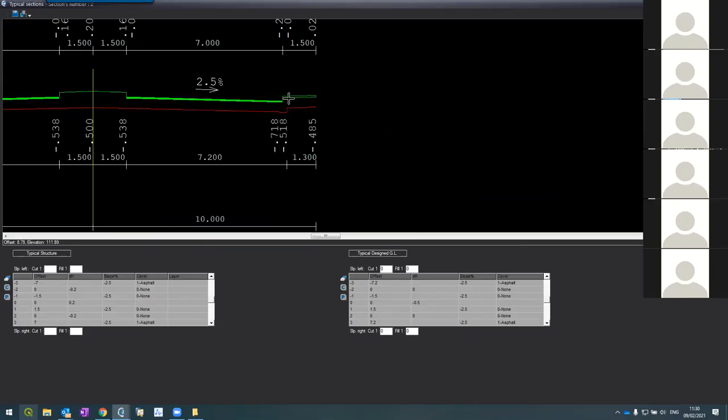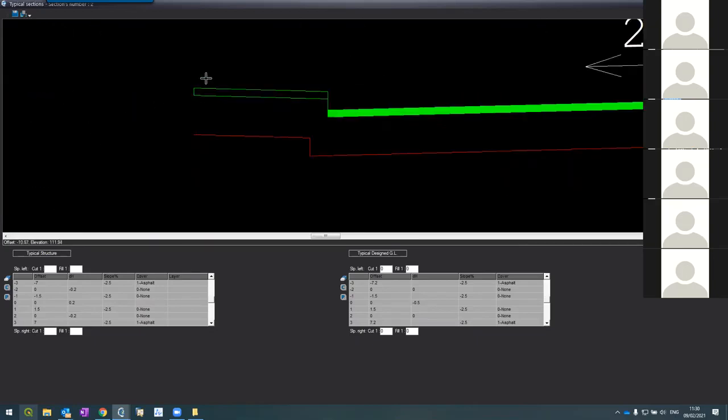Okay. But my structure level, actually the bedding below the path, below the sidewalk, is not 60 cm because I don't have subgrade. I have only sand here. No bitumen, nothing. So what I do, here this drop, it's not 20 cm. Let's say that the width here is 20 cm altogether, from here to here.